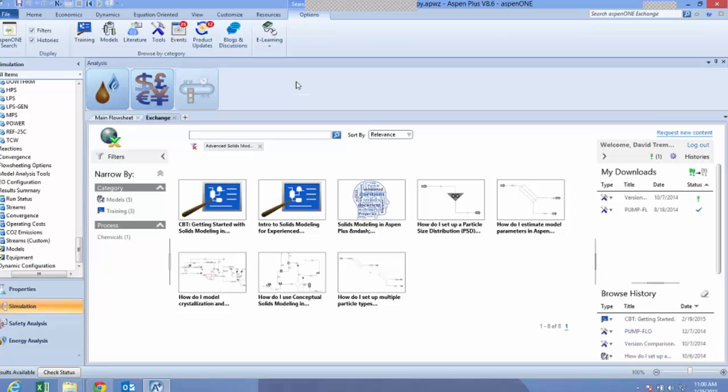Okay. Next question. So there's a question about the cost estimation, whether it's scale sensitive. Again, this system is using rigorous volumetric-based cost estimating. So it is certainly going to consider the scale of the process. And there are situations where if I have a very large-scale process, it will automatically decide that I need two parallel units instead of a single unit. It won't try to design a column or an exchanger that's bigger than you could physically make in reality or buy in reality. So it is cognizant of those types of issues.